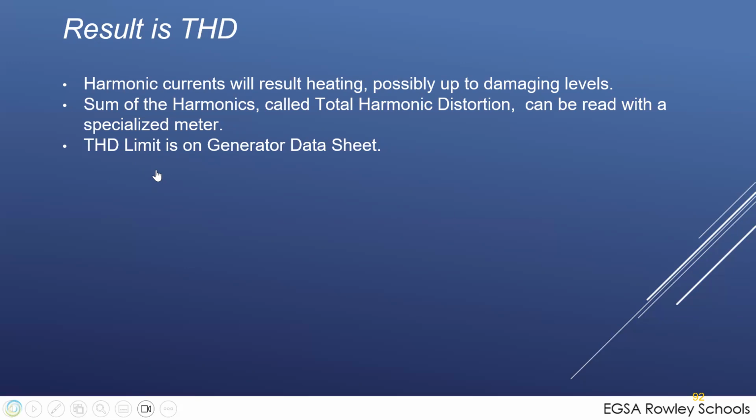You talk to your customer and say, like, your load, again, I produce a voltage. It may not be a pure sine wave, but it's pretty close. May have a little distortion because I may be a 5/6 or a 2/3 pitch machine, but my sine waves are pretty close to sinusoidal. And your load you're applying, Mr. Customer, is causing harmonic content to flow. And reacting with your load is causing this heating in your generator. It can damage your generator. So be careful of that.